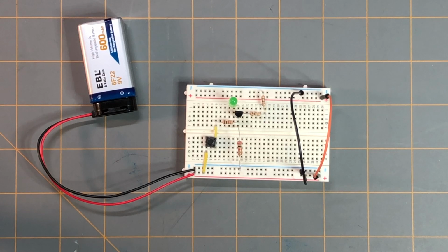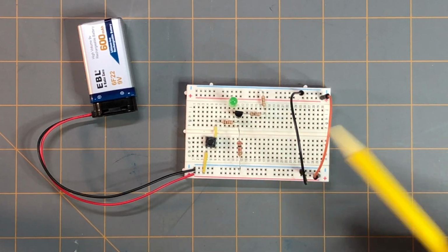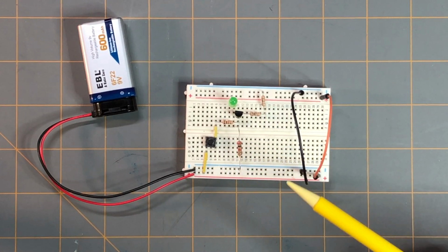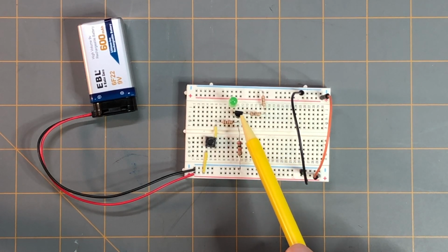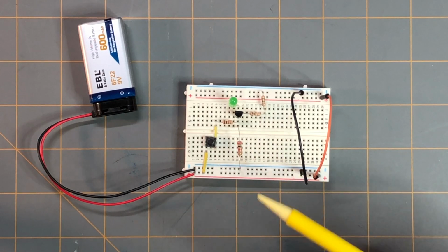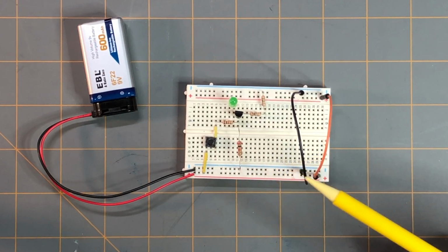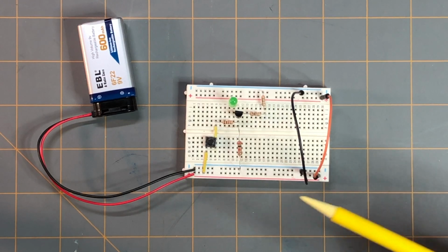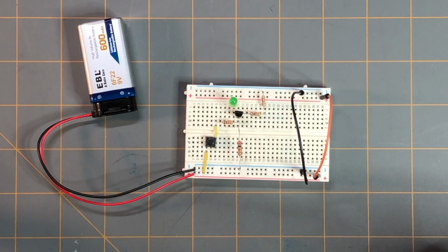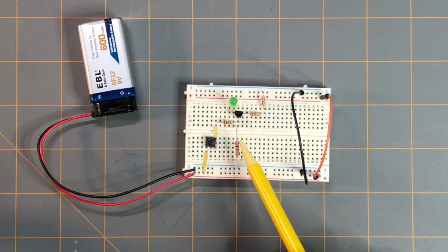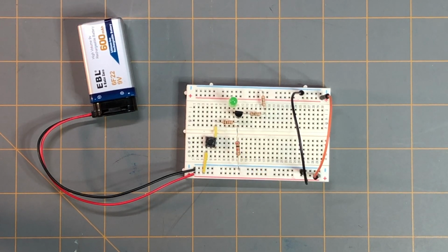And again, I'll leave all that in the description below. But you can follow along in that reading material and set up your own circuit just like this one for the switch application using the 2N7000 MOSFET. In that example, we're given some values of the circuit and we're asked to find some unknown values. In this case, we're asked to find the resistor value of R2, which is this resistor right here. This is the 2K ohm resistor, and that's the value that we found in that example problem. And we're also asked to find the drain to source voltage.